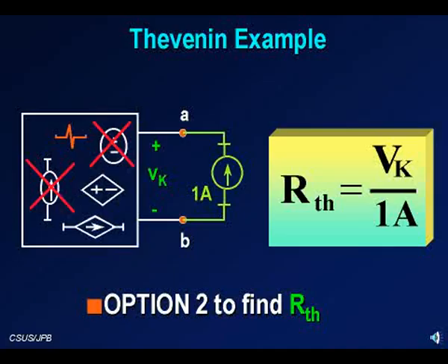This approach, I like it a lot because, in essence, that's what you do if you take an ohm meter and measure the resistance of a circuit. If you had a circuit that was connected, you essentially take it out or disconnect it from the electrical outlet. By doing that, you're turning off all independent sources. Then you go in and stick in the ohm meter.